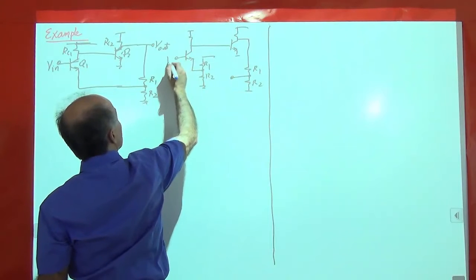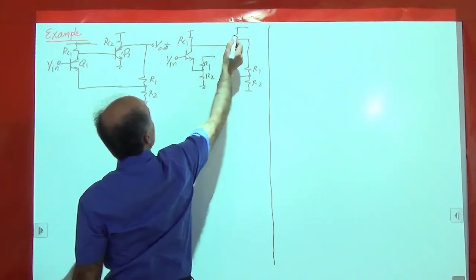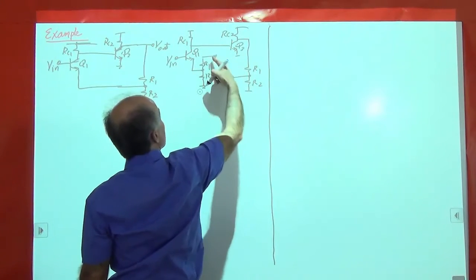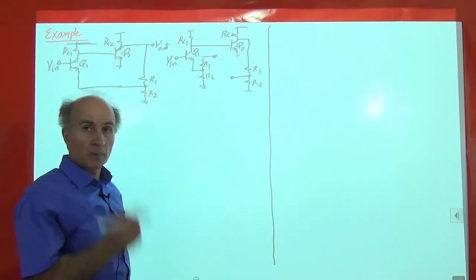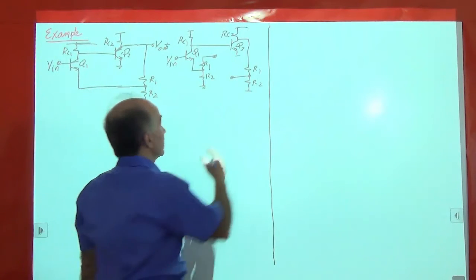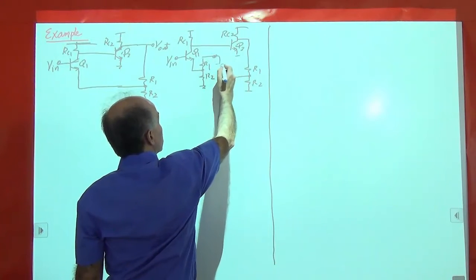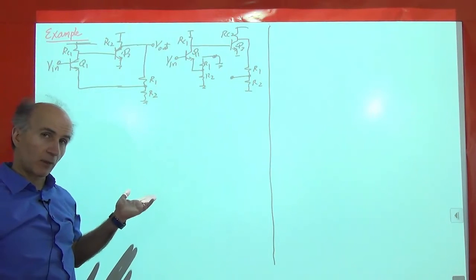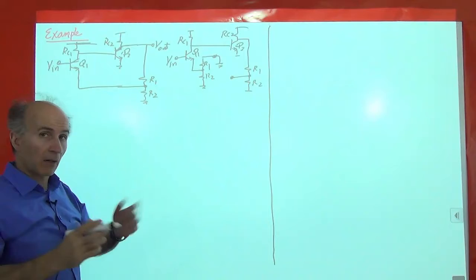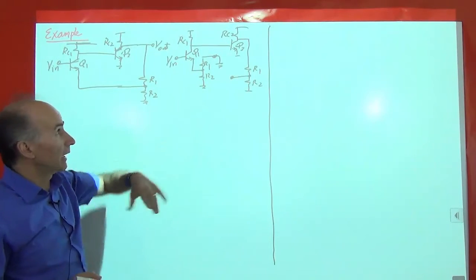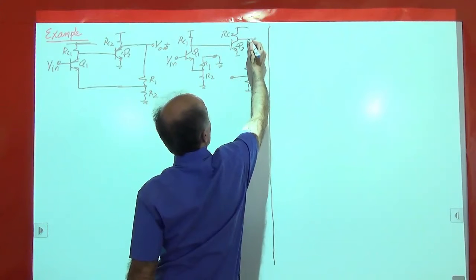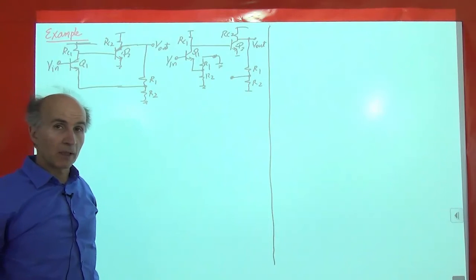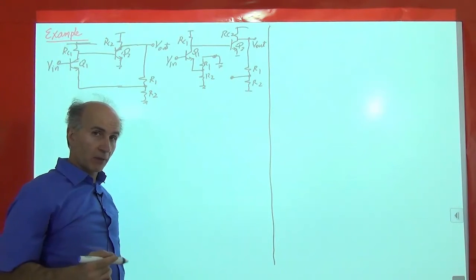Okay, so this is Vin, RC1, RC2, Q1, Q2. And what remains are these two ports. The table on the previous slide says that for this port, we have to ground it. For this port, we have to leave it open. So that's how we break the loop. Now I can go ahead and analyze the circuit. I can find the open loop gain, the open loop impedances, and so forth. This is really Electronics 1, so we should be able to do it just by inspection.